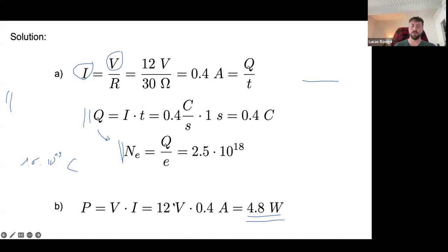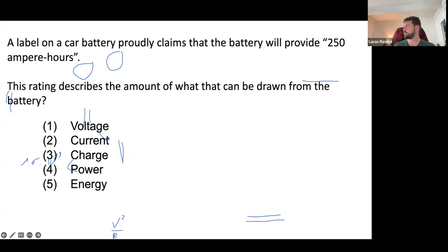So that seems reasonable. And we could have obtained that using just the resistor, using V squared divided by R, and it would have given us the same thing, just with a little bit larger numbers and a ratio to calculate, but it's basically equivalent, because to get the electrical current we just use Ohm's law, and this is based on Ohm's law too.